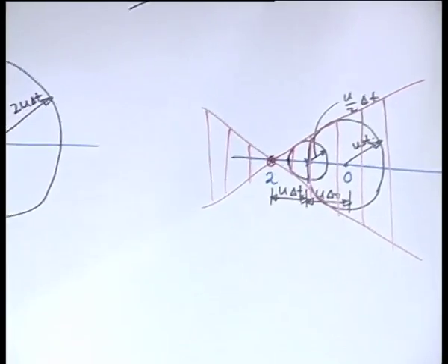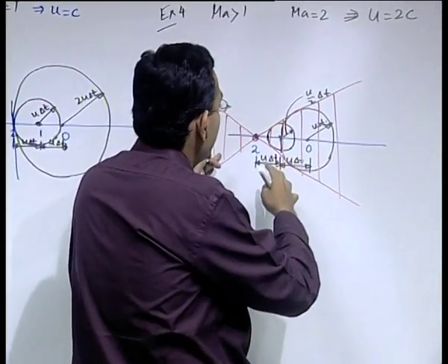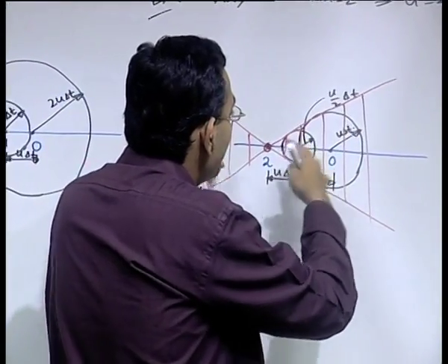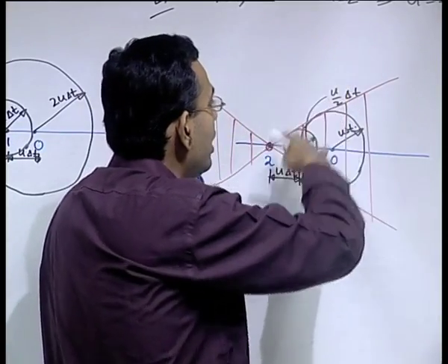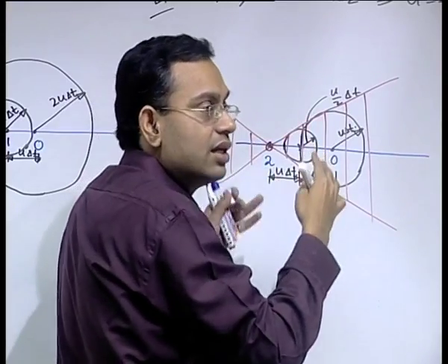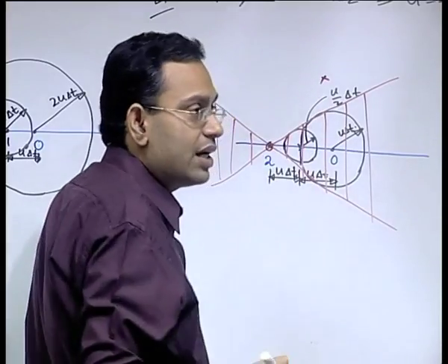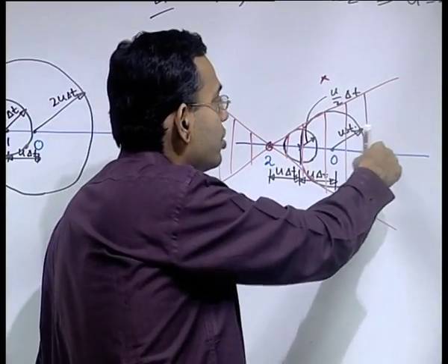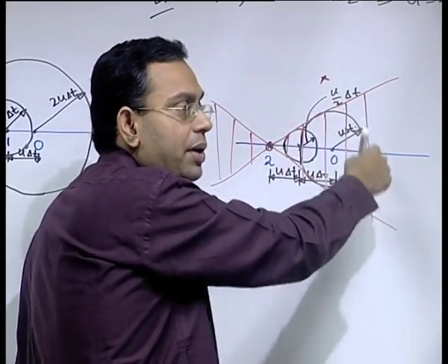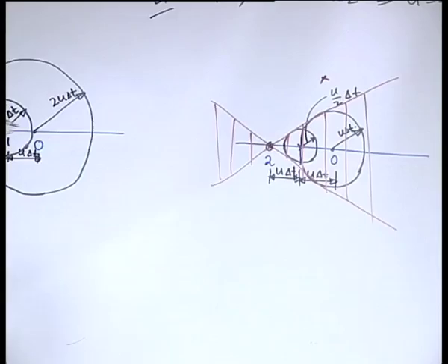So, what basically happens is that any disturbance propagates and makes its effect felt only within this zone. Outside this zone is a sort of zone of silence. So, if there is some observer who is located outside this zone, will not feel the effect of any source of perturbation, pressure perturbation within the domain because of the movement of the source of disturbance.